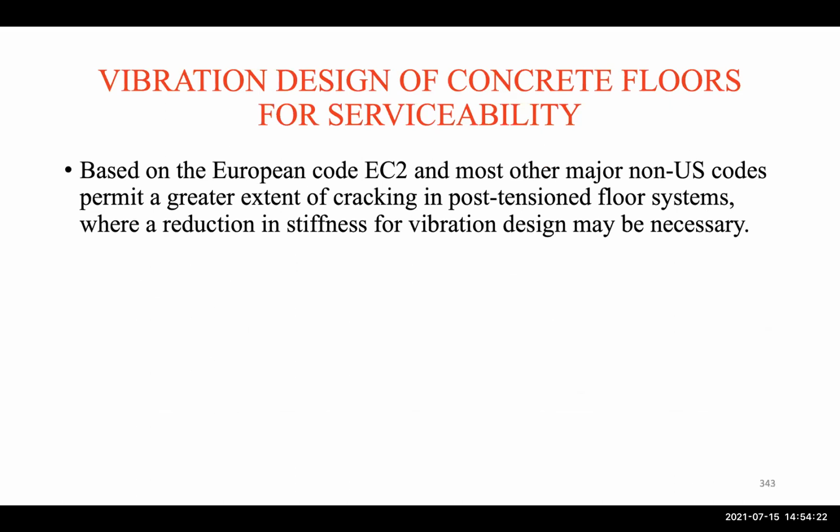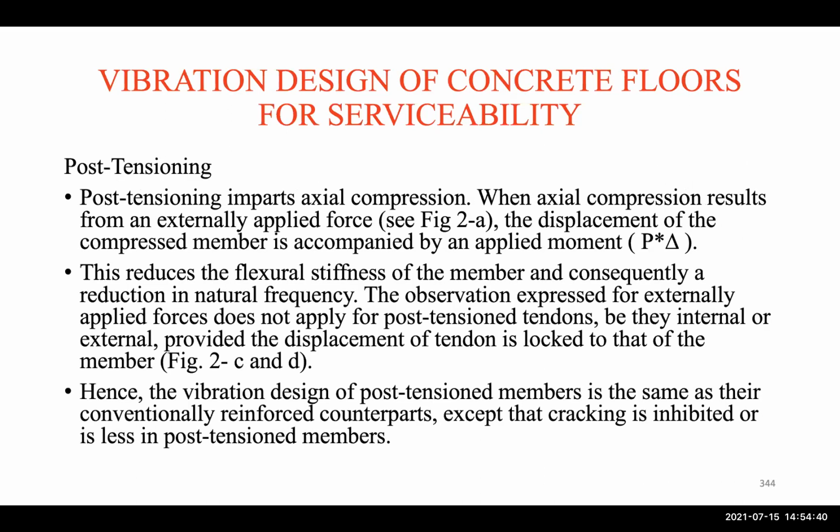So according to, for example, Eurocode 2, which is the concrete code, and most other major non-US codes, they permit a greater extent of cracking in PT floors. So there, deflection will become an issue and vibration will become an issue, because they are considered as cracked floors. Okay.